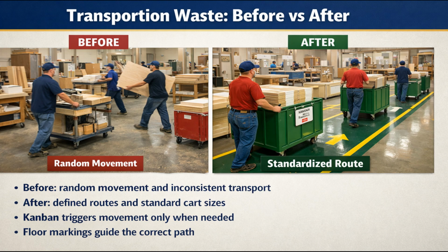Standardize transportation methods by mapping out the most efficient routes for material movement. Make sure tools for transportation are always available and suited for the need. Avoid oversized or undersized vehicles of transportation. Define limits on batch sizes. Use visual signals like color-coded bins or labels for different destinations, floor markings for staging, loading, or unloading zones.